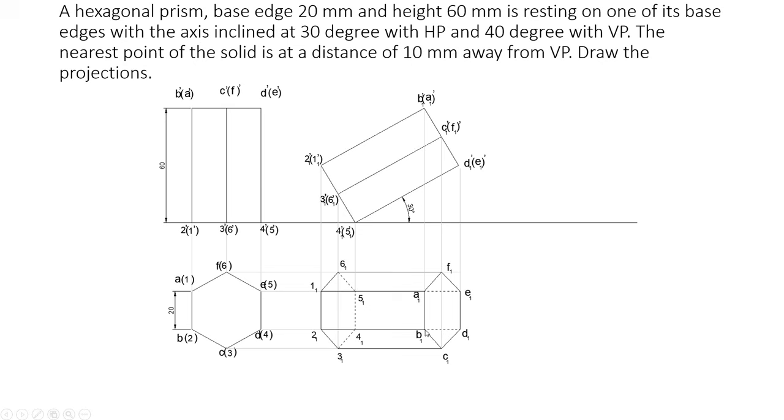So that means this line, this line, that is 5E and 4D, a part of that is visible. Since this 1A is visible, you want to mark that line as this much visible, and the remaining portion only dotted line. So the line 5E, only this much portion you have to use dotted line, and 4D, only this much portion you want to use dotted line. So the remaining lines 6-5, 5-4 and 4-3 will be invisible in the top view after tilting.